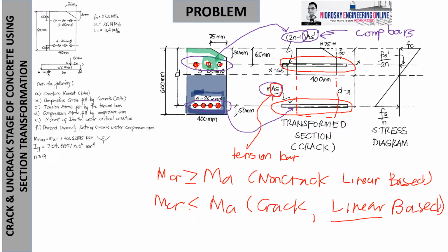The steel displaces concrete, making a hole in the concrete compression region, so there is force lost in the concrete compression. Therefore, we need to deduct 1, so 2N minus 1. Why times 2? Because the area lost and the area placed are equal. That's the short explanation.